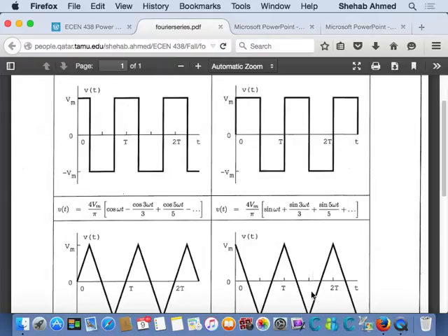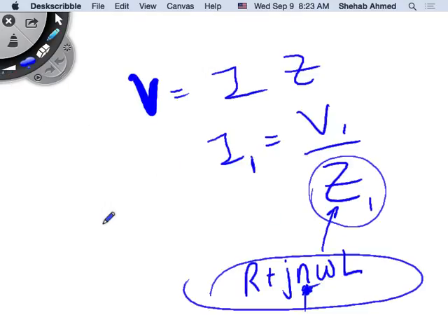So what happens is, as your frequency increases, your impedance goes higher because of this. And your voltage goes lower because you're always dividing by this harmonic order. So for the 100th harmonic, you're taking that voltage and dividing it by 100, right? And you don't have a voltage waveform that is the 100th harmonic. The majority of it is actually the 50 hertz. You just maybe have some ripple on it that is causing some 100 hertz, 100th harmonic content in there. So the voltage content is small at that frequency, and the impedance becomes larger at that frequency.